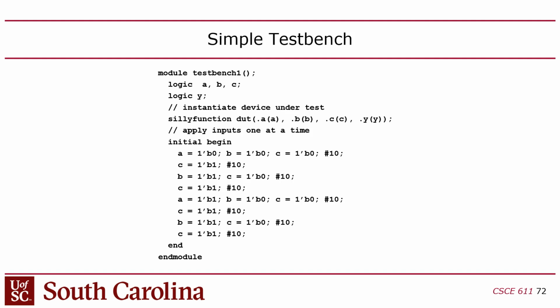So doing this delay thing makes this non-synthesizable, but it'll work in the simulator, and when you're happy with it, then you take the thing that you're actually testing and you put that in the hardware. And then presumably you're wiring A, B, and C to some wires coming from the outside world or from the module, right? Okay, you guys with me?